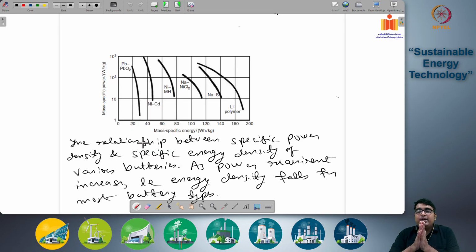So that kind of ends our battery performance characteristics. We discussed how the current voltage curve and the power curve look, how there is a trade-off between energy storage and power delivery in batteries, how to evaluate the round trip efficiency, what is the importance of the electromotive force and what is the importance of the internal resistance.